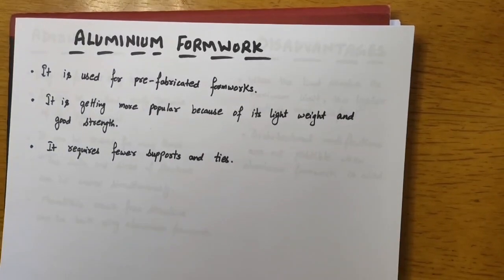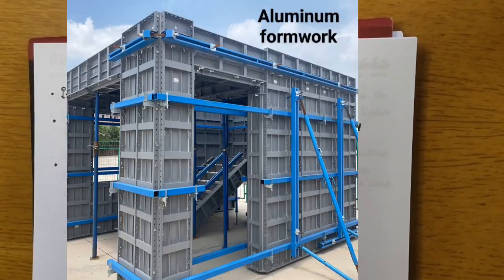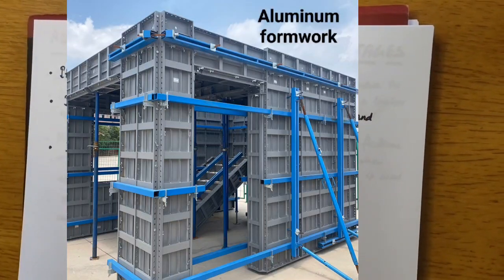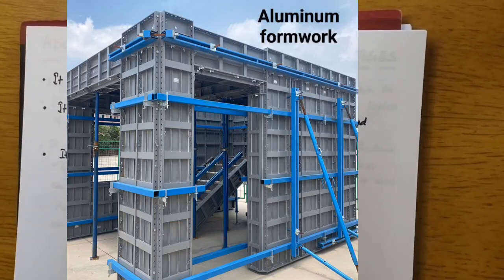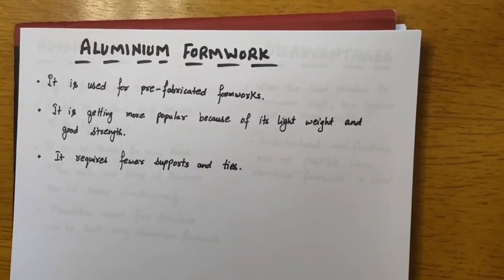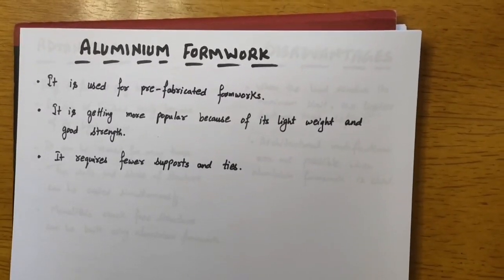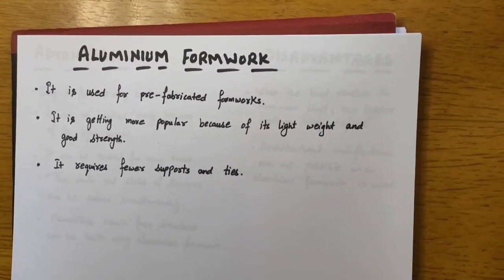Let's move to aluminium formwork. It is used for prefabricated formwork. So we generally prefabricate this kind of formwork and then we pour the concrete inside them. It is getting more popular because of its lightweight and good strength. So they are very light in weight, so it is easy to carry them and use them, and they have good strength. It requires fewer support and ties. So as compared to the other formworks, they don't need more vertical and horizontal supports and ties.